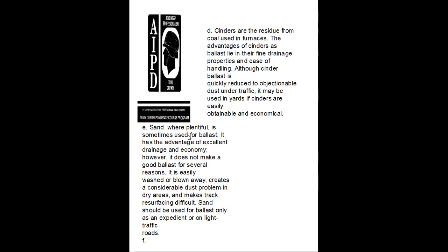Cinder ballast has fine drainage properties and is easier to handle, although it is quickly reduced to dust under traffic. It may be used in yards, and cinders are easily obtainable and economical. Sand, where plentiful, is sometimes used as ballast for its excellent drainage and economy.